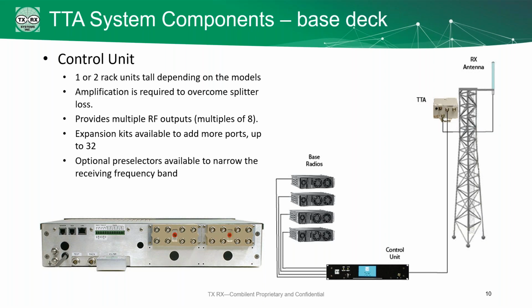We also have optional pre-selectors that we can use to narrow the receiving frequency band. This is useful if you're in a crowded radio environment and you've got a lot of other people talking on the same frequencies that you are.